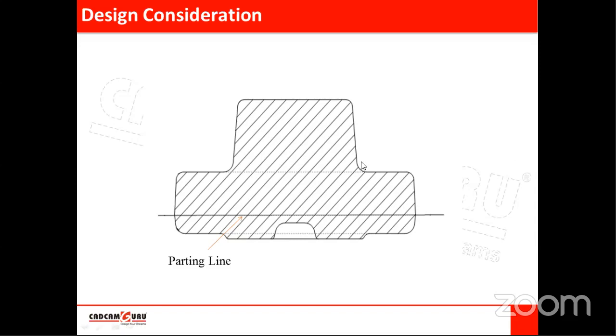So there will be two flanges, right? This is one flange actually. The other one will be similar, just fitted on the opposite shaft, driving shaft and driven shaft. That's why we need power couplings. Couplings are fitted on the power transmitting shafts. If you want to connect two shafts, then these types of bush couplings are used.